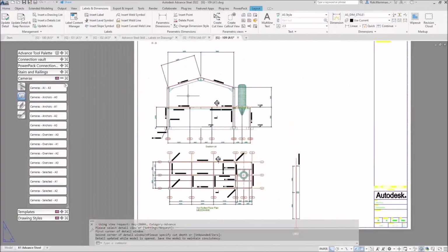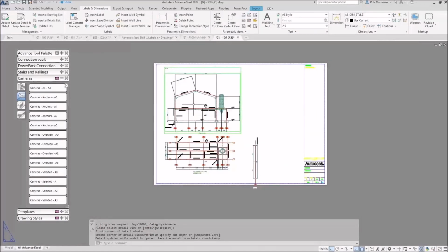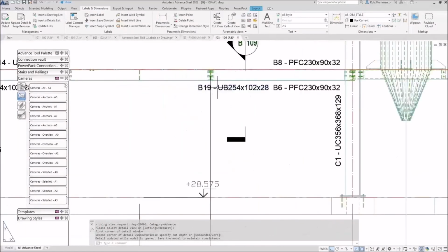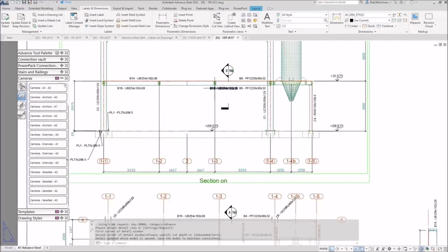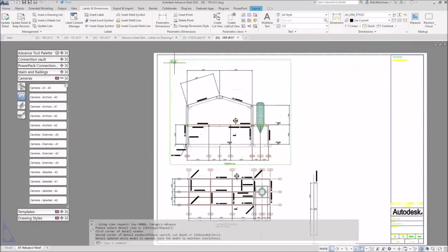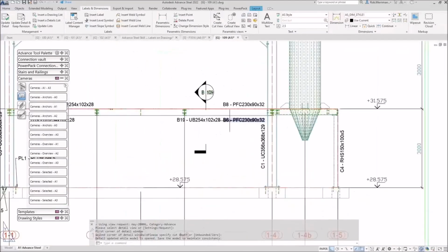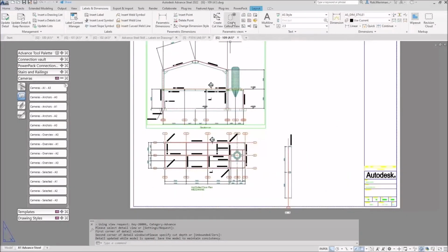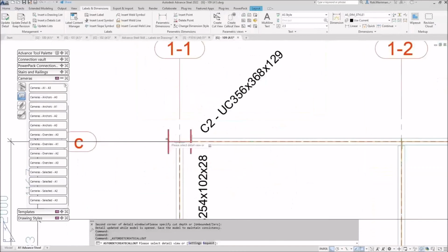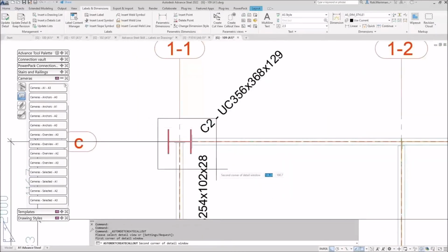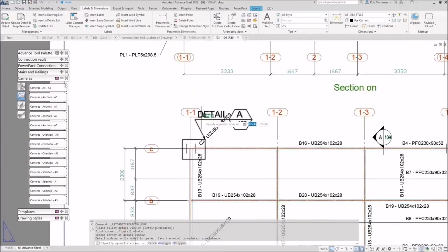And then we have section B. Because it's a section through a certain bit, I've obviously not set the depth to actually show it, so I've not got the right depth settings on my cut view, but there is section B and section B. And the same will work with the call out views. So although the management default said cut views, the call out view, which is our blow up option, uses the same information. So that is detail A,